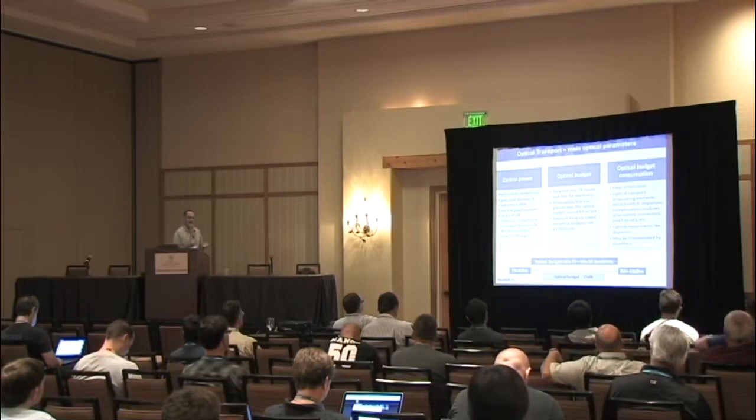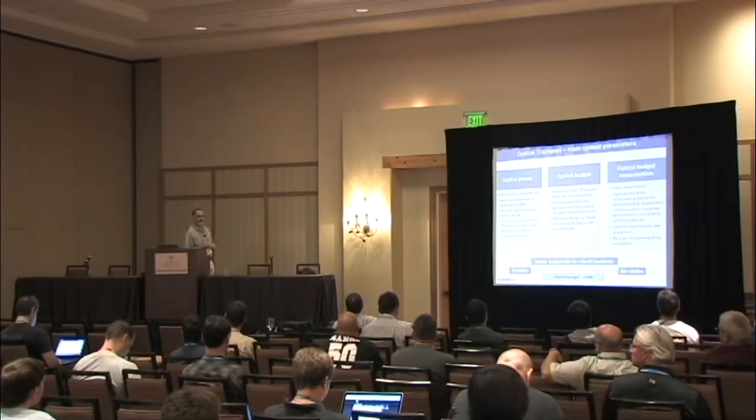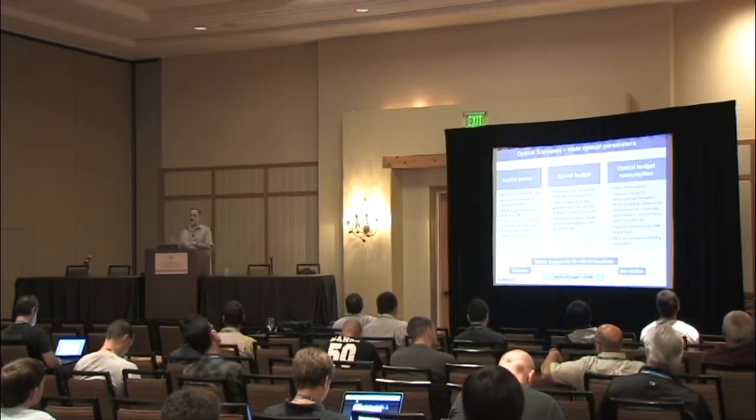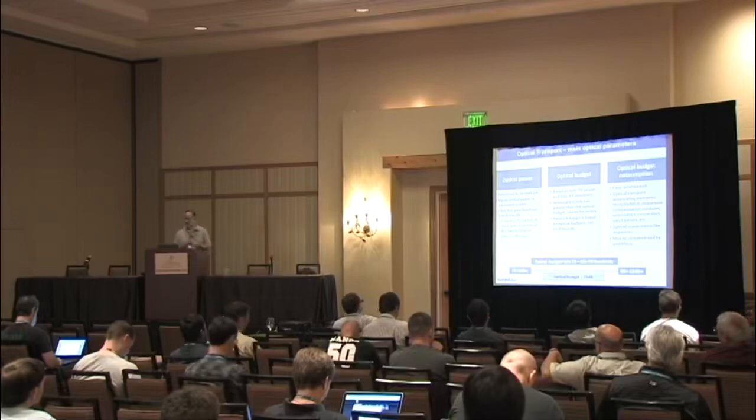Anything that generates attenuation. The main culprit is the fiber loss. You have 10 kilometers of fiber, it's going to generate fiber attenuation. Then you have all the other elements that can be simple attenuators or mux-demuxes or dispersion compensation modules, connectors, splices. Everything that is on the way is going to generate attenuation, is going to consume your optical budget.